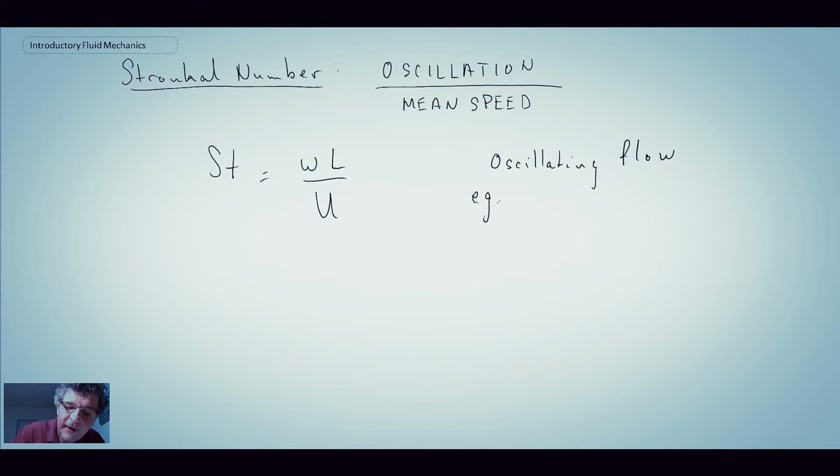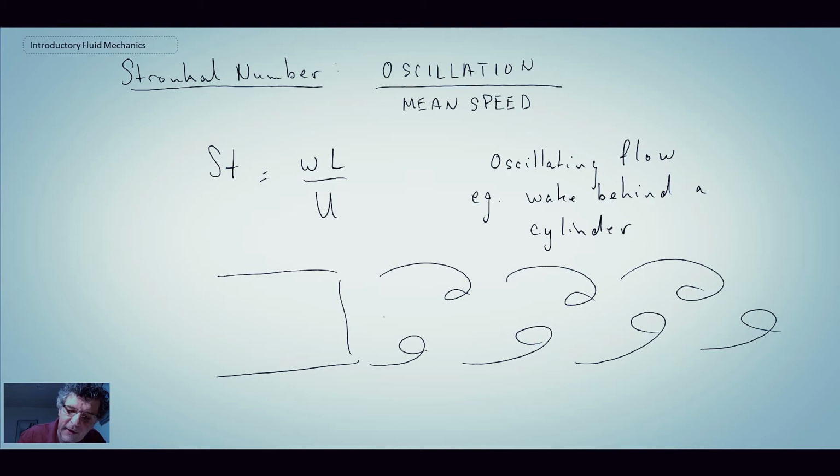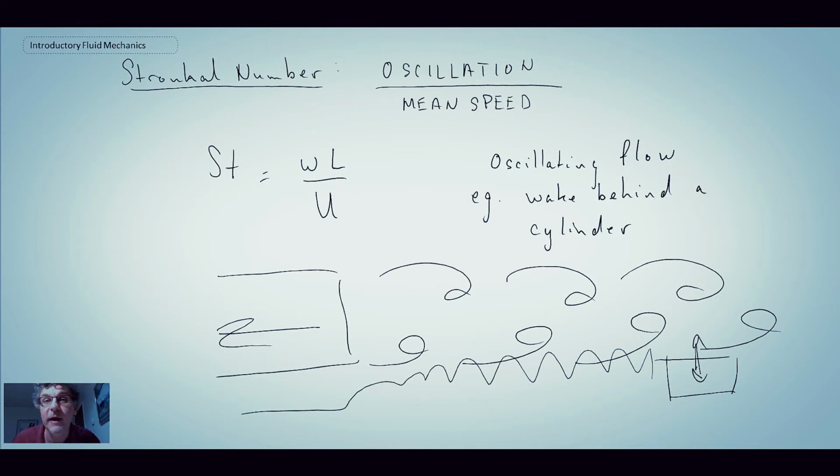An example of this that is well studied is the wake behind a cylinder. If you ever follow behind a semi-trailer truck on the highway, what's happening is we have large-scale vortex structures coming off, and that is oscillating, so the vehicle is moving in that direction. That's why your car, as you try to pass one of these big vehicles, you feel it pulling left to right, and you get instabilities as you drive through this wake, and then as you get by, you get cleaner air when you get up and along parallel. So that is a Strouhal number.